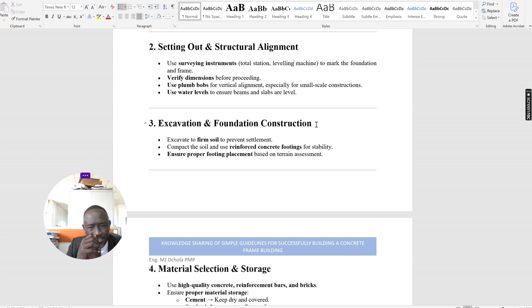Once the setting out is done, carpentry work is done, reinforcement is done, and checking is done, then the concrete guys come. Once concrete is cast, I'm telling you, when they strike off the column formwork, you have to see the beauty of your concrete. If it is not plumbed, then it becomes visible, and also very risky for use. So you have to be careful; our site must have close monitoring, especially when you're doing a concrete frame.